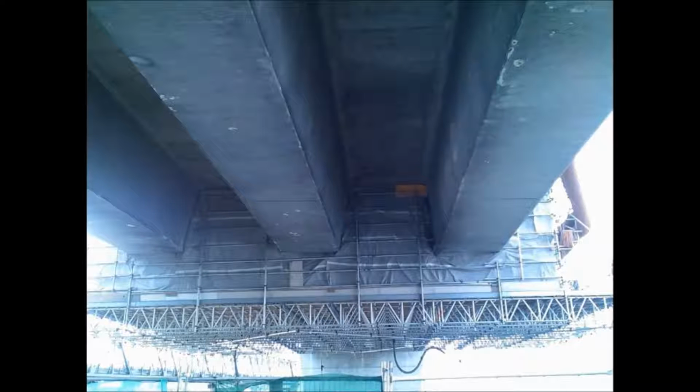Using a blast sheet, this may also need to be fire retardant grade, and it needs sufficient airflow as cross-draft and downdraft as outlined in the Australian standards for design recommendations. To further the requirements, there needs to be an adequate ducting system to go back to a huge commercial dust extraction fan. You can see the duct there on the right-hand side of the photo in red.